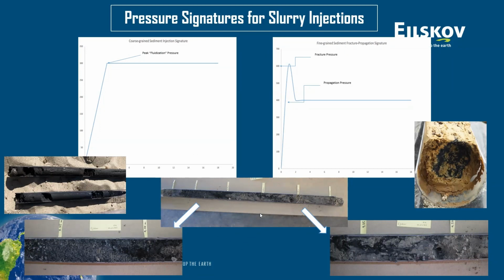The pictures below show a nice transition zone from a gravelly sandy formation to a hard clay formation, where we can see the distribution being more homogeneous on the left end in the sands and gravels, whereas in the tight clay formation, we have a more tree root type of distribution, and that shows how the materials try to propagate in soils. And there again, another nice core of a clay formation, where you can see a nice perpendicular cut within the core of how the slurry is distributed.